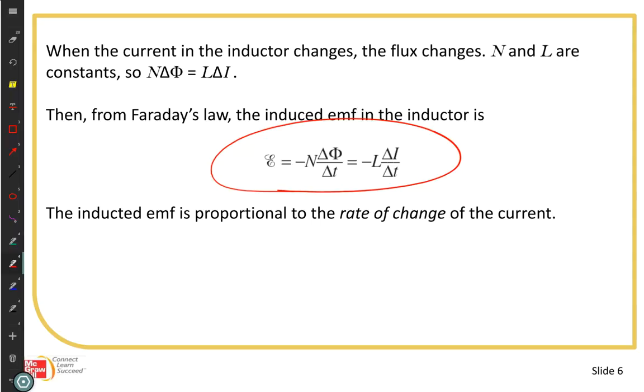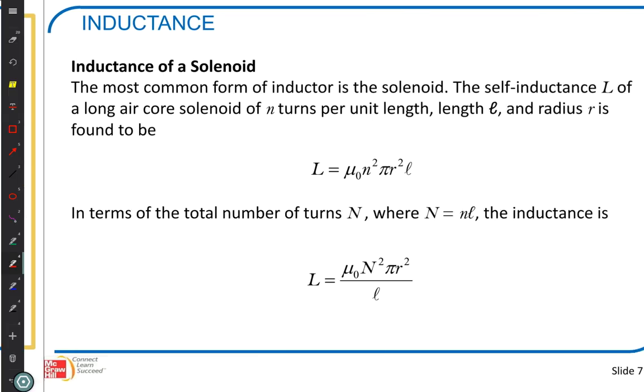So that's how we use an inductor in a circuit. It's going to create a magnetic field and store energy in the form of a magnetic field. And then it will give that energy back, just like a capacitor gives the energy back. An inductor doesn't use power or energy. The average power for an inductor should be 0. The average power for a capacitor should be 0 because they store energy and give it back. So in our circuits, that's going to be an important thing.